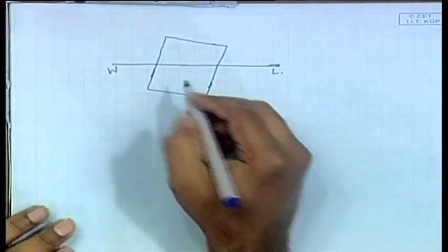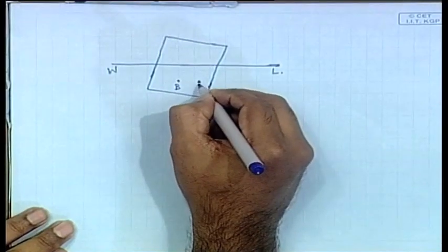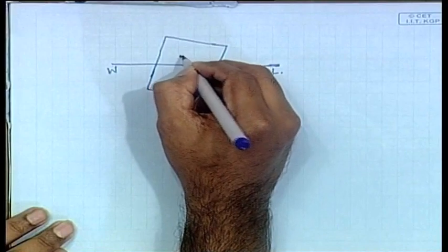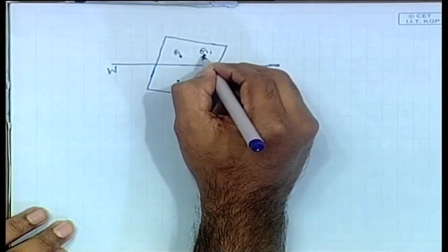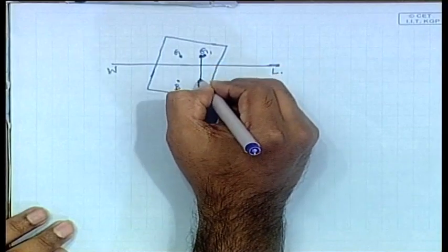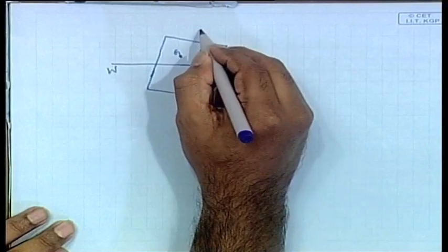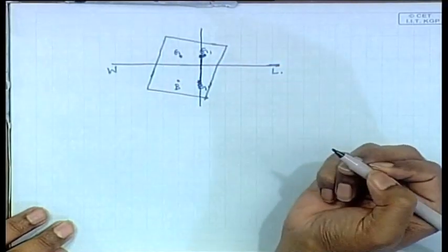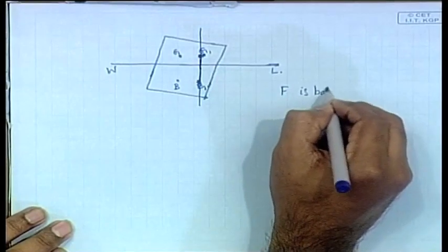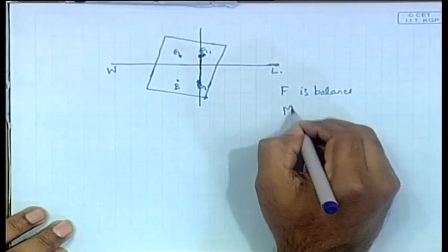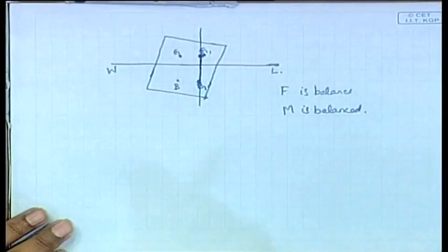So, it is tilted such that B, this was the initial B, has now shifted to this point B1, G was initially here somewhere and G was shifted to G1. It has finally come such that its G is here and it is in the straight line. Okay, this is the straight line. Now, it is in equilibrium again, forces are balanced, moment is balanced.